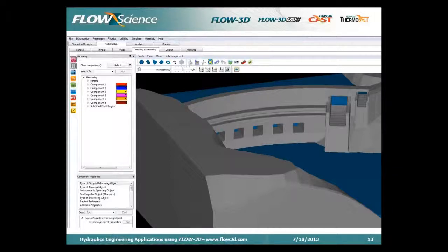So in Flow3D, objects are free to be placed anywhere within the mesh without any remeshing at all being required. Of course, you can nest finer meshes within coarser meshes in order to resolve finer details. The basic premise, though, is what we call free gridding, which is a very, very powerful feature of Flow3D. So if you change your geometry, you do not need to remesh anything at all. Things just float in space.